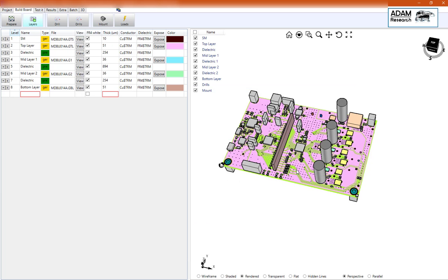This is how the model looks. The data come from the Altium files, which are available on the website or from Texas Instruments. It's not a problem to get this into the simulator. We see here in blue the pin for VBAT and in red the pin for ground. All these yellow components can be flooded with electric current so that the loop is closed.